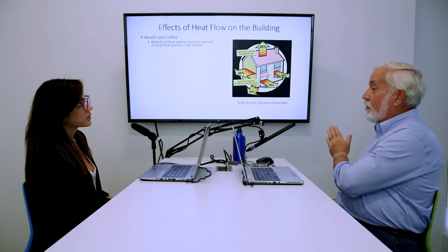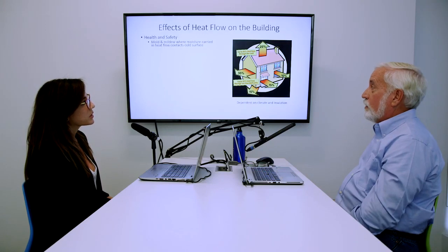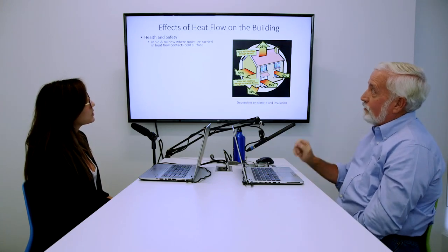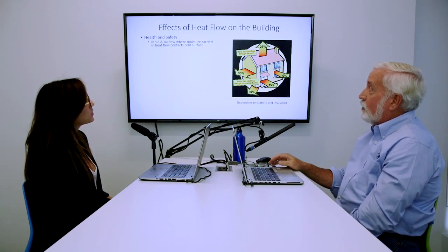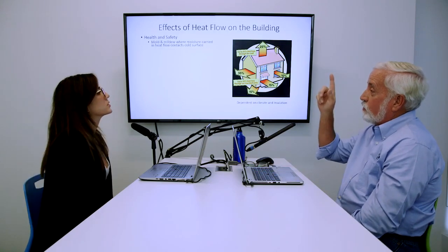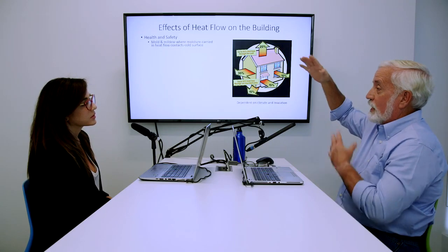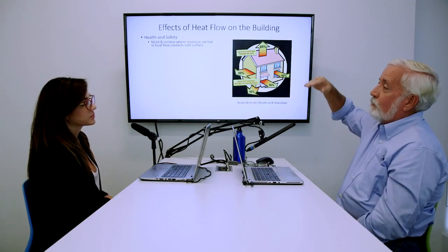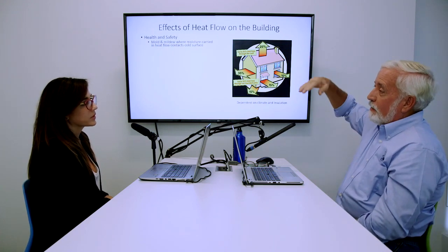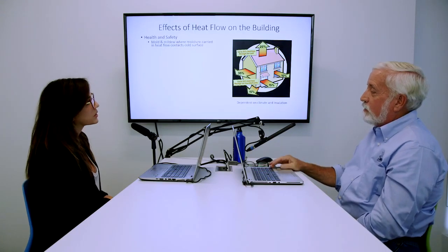So whether it's air or heated air, we're still going to move moisture, and we're going to have the same problems, and we still will have mold and mildew where moisture is carried in a heat flow. And where we really notice this is going up through roofs. We have a lot of buildings that are built without trusses and attics, and so they just have a big rafter that will rise with that heated air through the insulation, and we have a mold issue on the underside of the roof deck.